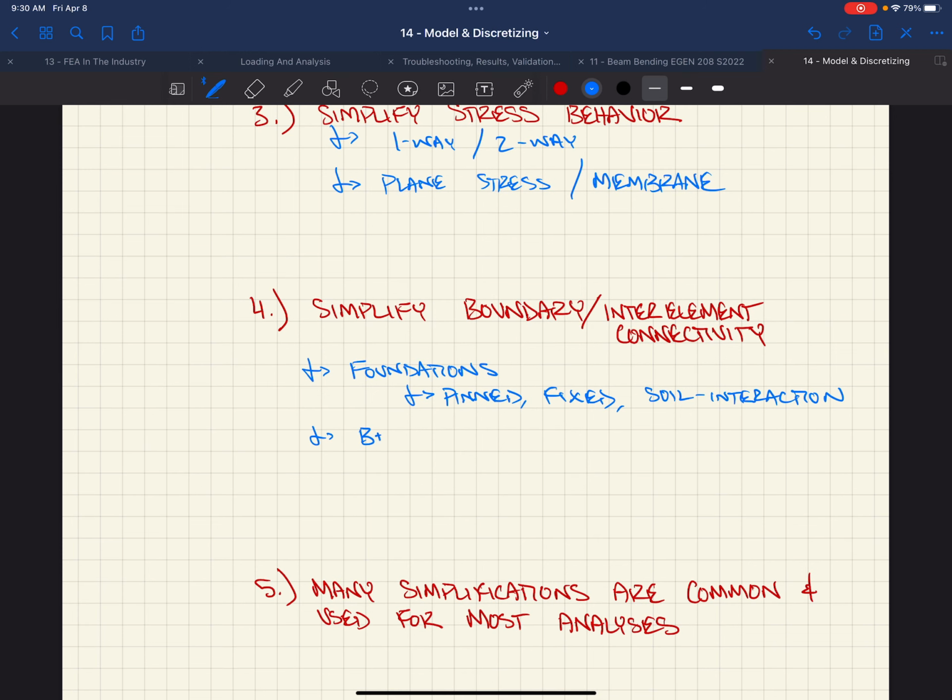What do we do at beams to beams? We make some simplifications. We make them pinned connections if they're shear tabs. Have you gone through partially restrained moment connections in steel yet? I don't know that we're gonna get there. There's a whole section about PR, partially restrained moment connections. Those would not be perfectly fixed. Fully restrained are generally what we deal with. But in some cases, maybe you have a partially restrained one.